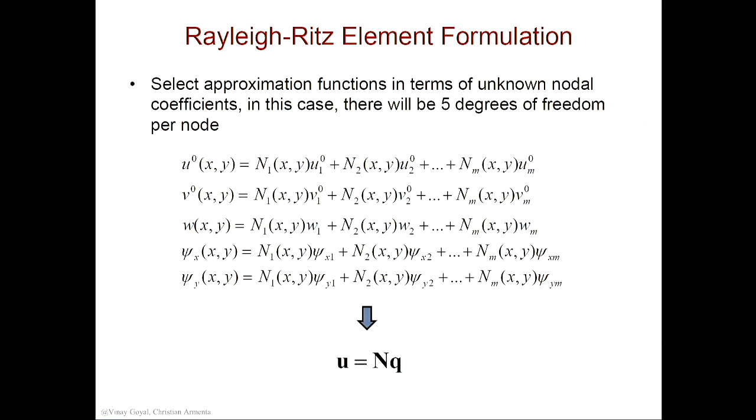But instead of that, we'll use this approach, which is finite elements. Now I'll take the displacements and interpolate them, so my unknown coefficients become the nodal unknowns. And I will also use shape functions that are the same for all of them, and these are my basis functions now. They'll satisfy partition of unity. I can do a quadrilateral with this, I can do a triangle, I can do a second order element and so forth.